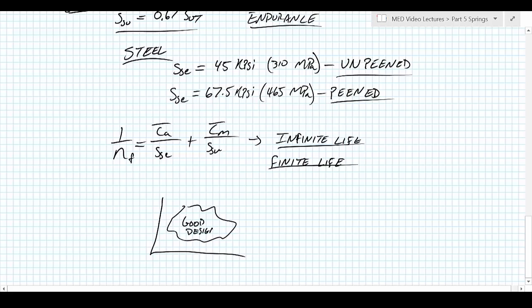That is, what are the springs that will work for us and give us the performance that we want in terms of the working range, the forces that go into it, the cost, the life that we expect out of it, and what we want to then rule out is anything that's going to cause yielding or early fatigue failure, natural frequency problems, and stability issues.